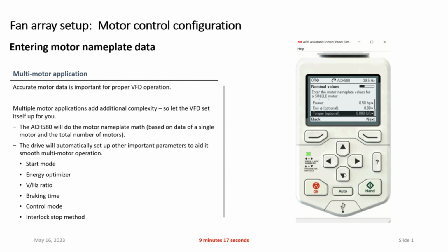So there's some other information. It's not too critical. Things like your power factor, you can skip over that. Now I'm going to come into here and hit next. So I got my summary. It's telling me I got 2 motors. Each one is a 1/2 amp. Each one is a 1/2 horsepower. Then it tells me, hey, combined, all my motors together are 1 amp and 1 horsepower. Now you can see why I picked easy numbers to make the math easy for us.